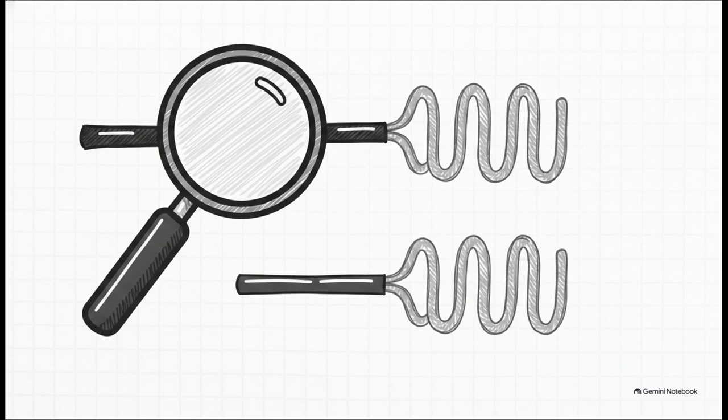If you've ever stared at an equipment nameplate and seen strings of numbers like 100/5/5/5, well, each of those slashes and numbers perfectly decodes exactly how many separate secondary windings are packed inside that one single transformer housing. So in that first example, a 100 amp primary is feeding 3 totally separate 5 amp secondary windings. But it kind of begs the question, right? Why on earth do we need so many separate cores?